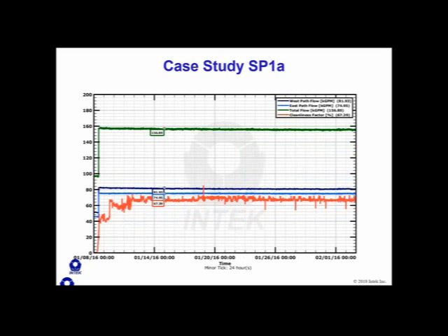And it turns out that they had a delivery of gravel to the plant, and the delivery vehicle got too close to the cooling towers, dumped a lot of the gravel into the basin of the cooling water towers, and all of that gravel got pushed to the condenser when the circulating water pumps came online. And so this may not have been noticed without this instrumentation. There's no way to know, but I've seen it time and time again where a situation like this goes unnoticed, especially cooling water debris fouling.